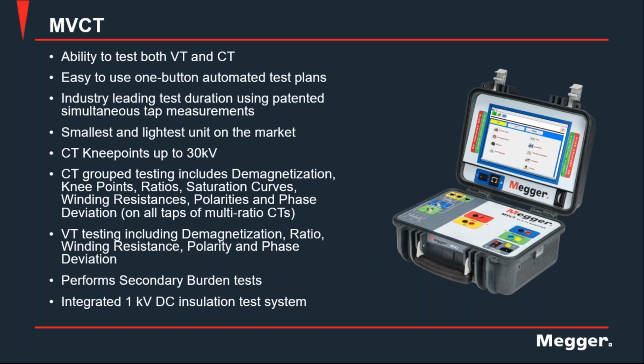And the MVCT is a lighter instrument that uses a different technique for the saturation. There are some CTs that will saturate, will have that knee point, at 30 kilovolts or 15 kilovolts, and then you will need higher voltages to test that.